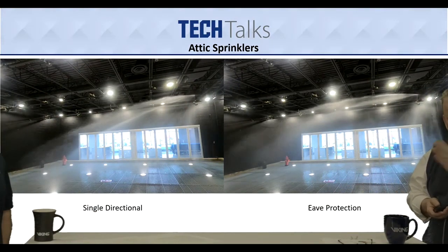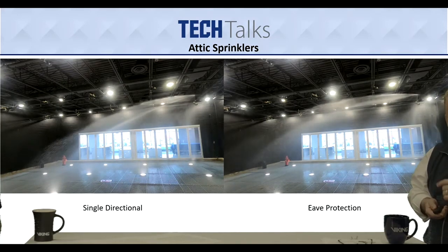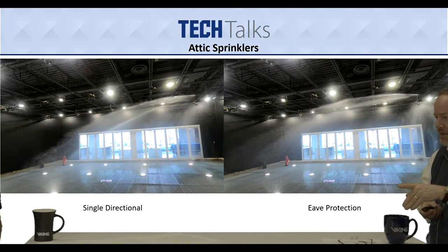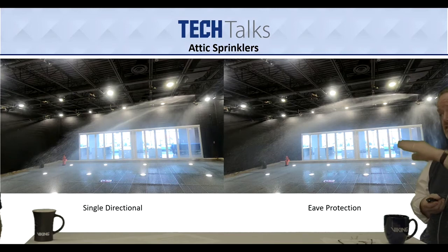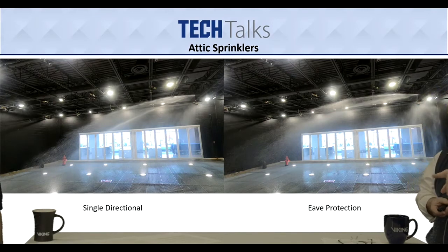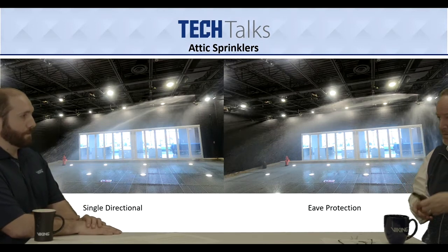So here's the distance you were talking about. On the right is the Eave protection, and on the left is the single directional. They look kind of similar, but the Eave protection one is intended to be installed along the slope of the roof, like any other sprinkler where the deflector is parallel to the slope. Whereas if we were to take the Eave protection one and angle that down the slope, we would see a dramatic difference in these two spray patterns.